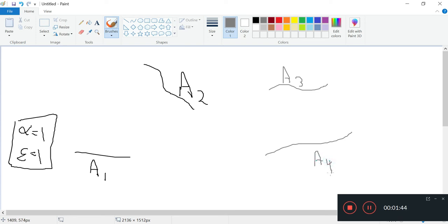So the more important case is if you have two surfaces where the heat transfer between them occurs, and both of them are not black. This means they are either some kind of steel or shiny surfaces or something like that. So these are non-black surfaces. The absorptivity and emissivity here will not be equal to 1.